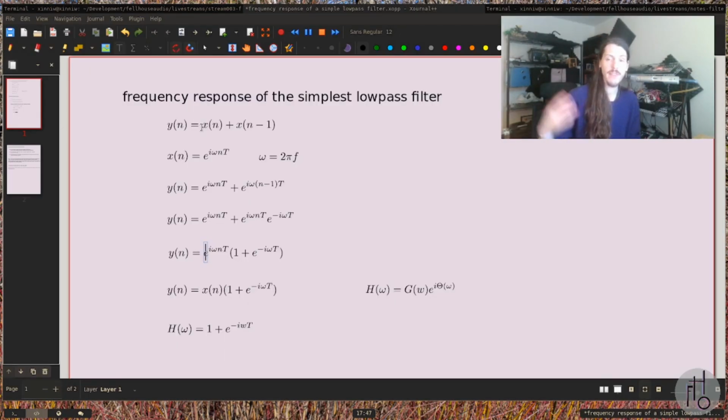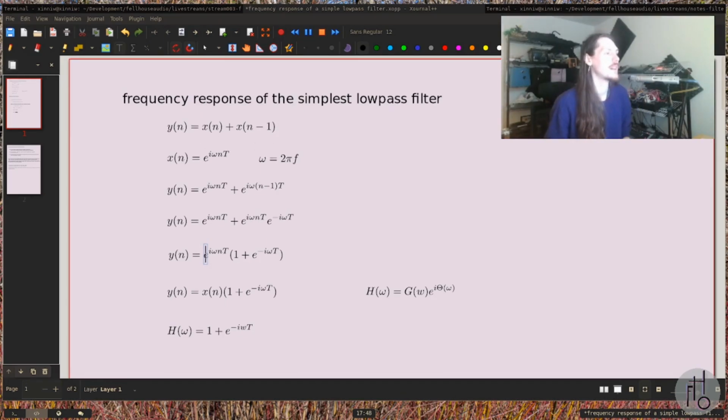It's what's called an FIR filter, or finite impulse response, because it only deals with input samples. An impulse response is where we feed a filter the following signal: 1, 0, 0, 0, 0, and then the rest of them are zeros. The impulse response is what we get when we actually feed this signal to the filter. So, if we talked about the values of this over time, we would get 1 plus 0 is equal to 1.